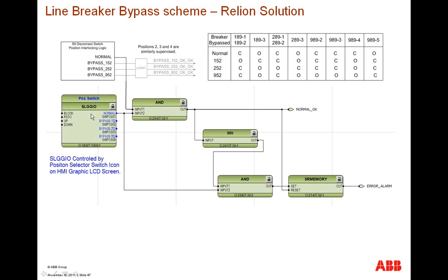So when the operator believes he's in the correct position or a normal condition, he must go through this AND gate, and if the A and B fingers, based on our configuration of the system, agree, we will satisfy this AND gate, and we get positive acknowledgement that we are actually in a normal configuration based on the switch condition and station condition.